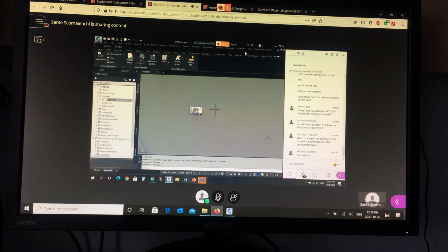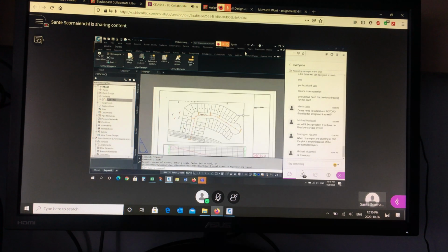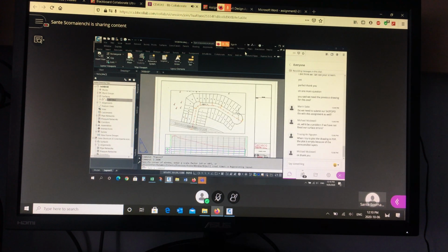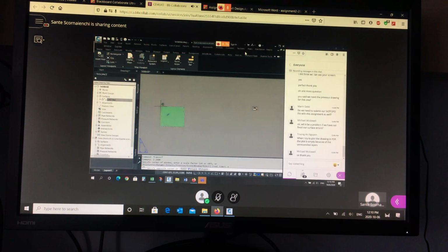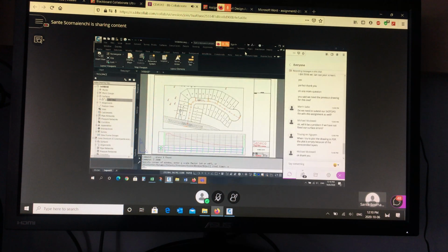So if you zoom extents and you see this effect, it could be on either side. You might have junk out here somewhere. Zoom extents. If you're not zooming extents and seeing this entire window, then you're going to have that problem. So zoom extents, and if there's what I call space junk out here, delete it. Zoom in. If you see everything, then it should be fine.